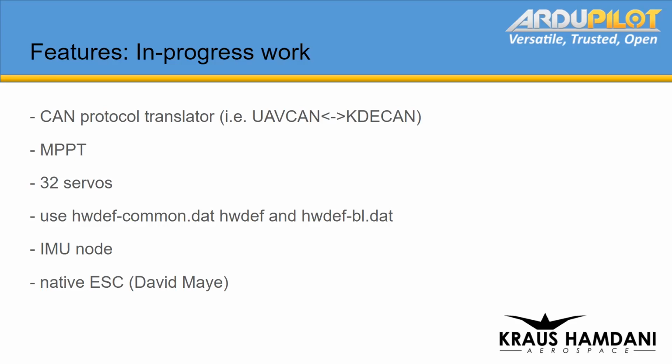It's also got a lot of automatic tools that allow you to use the ESC to make measurements on the motor to define the FOC. There's actually a tuning process, like an auto tune. You connect the motor and run a test, and it measures the required components to build the FOC model. Interesting.